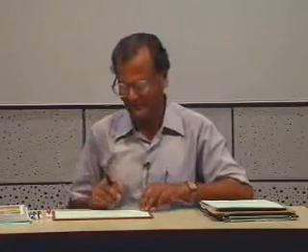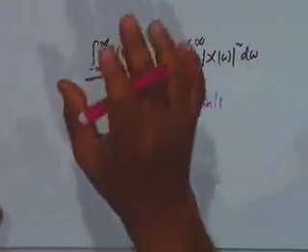Even then, the Fourier transform exists, and these are the alternative set of conditions given by Dirichlet. That is, the signal must be absolutely integrable, with conditions on maxima, minima, and discontinuities or continuities or the lack of them. Signals in which the energy is finite, we shall now introduce a term, are called energy signals. So Parseval's relation is valid for energy signals only. Energy signals are signals in which the energy is bounded.